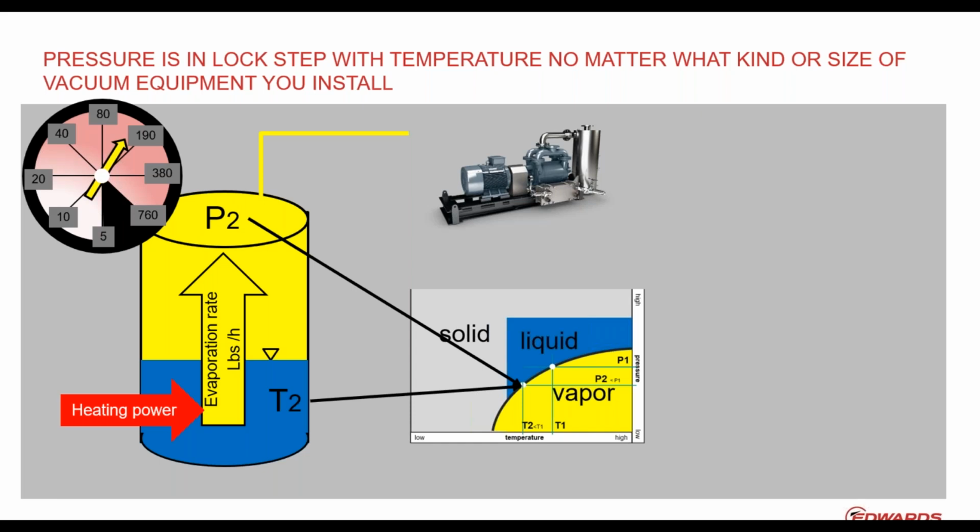But that drives the vacuum capacity mostly being too high, because everybody is concerned that too little capacity would mean you slow the process down. What that means is, if you have too much capacity, the vacuum pump is basically just tipping the process to the other side of the pendulum. So you have so much evaporation rate that the heating power can't keep up with it, and the temperature in the liquid would go down, which I've seen slow processes down significantly. So that's just an interrelation that I want you to be aware of here.